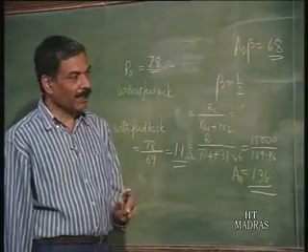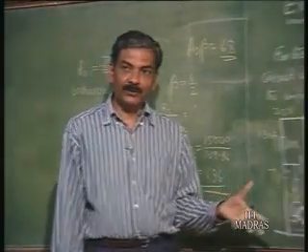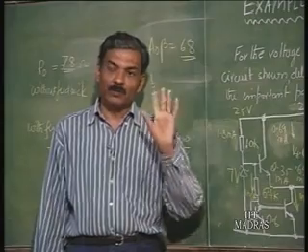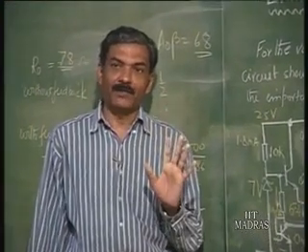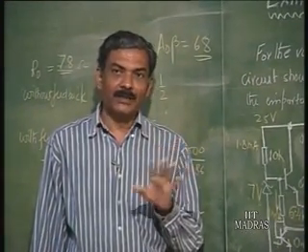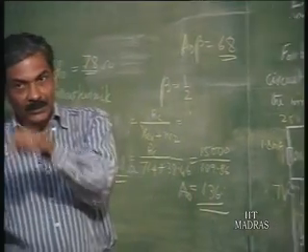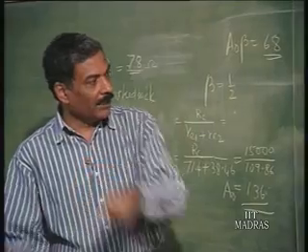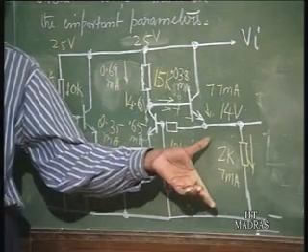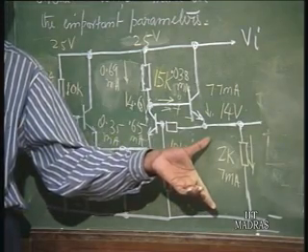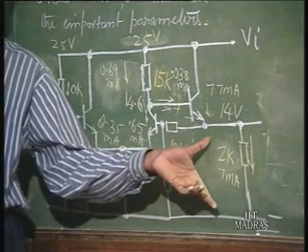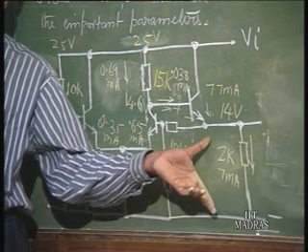This has to be borne in mind, because this regulator may be used for high frequency applications. So, output impedance is important only for high frequencies, low frequency output impedance is of no significance, right. How much the circuit that is being supplied this power is seeing, that impedance becomes important only at the frequency at which the circuit is functioning.